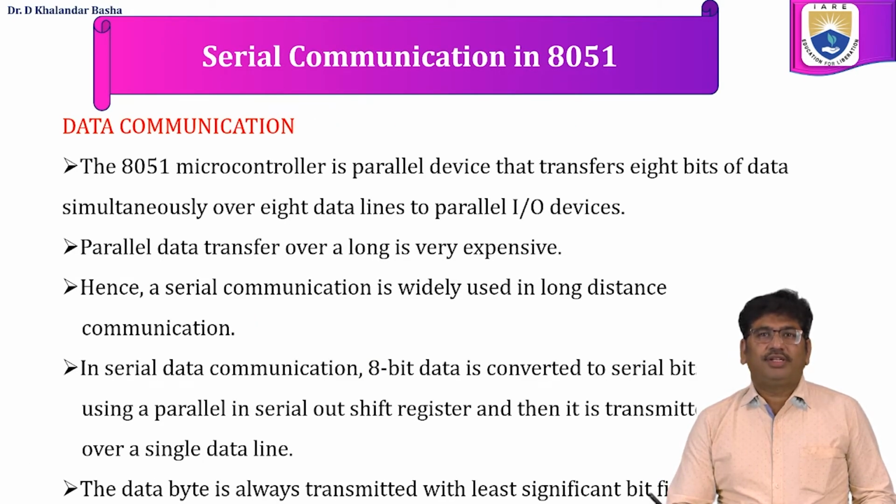The serial communication in 8051, the data communication. The 8051 microcontroller is a parallel device that transfers 8 bits of data simultaneously over 8 data lines to a parallel I/O device. Parallel data transfer over a long distance is very expensive. Hence, serial communication is widely used in long distance communication.